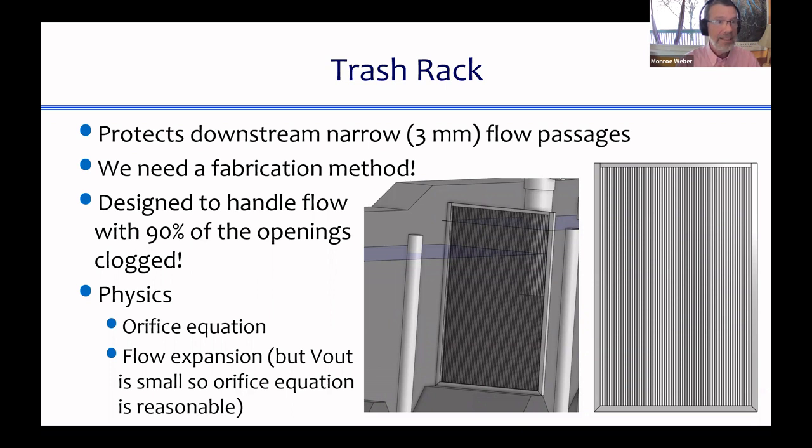We weren't being detailed enough in our designs. We weren't providing a design that looked like this even. It was even less detailed than this. And so our partner in Honduras was trying various things to make a trash rack. And often the porosity, meaning the fraction of the open area, wasn't high enough in the systems that they made. And so the head loss was too high.